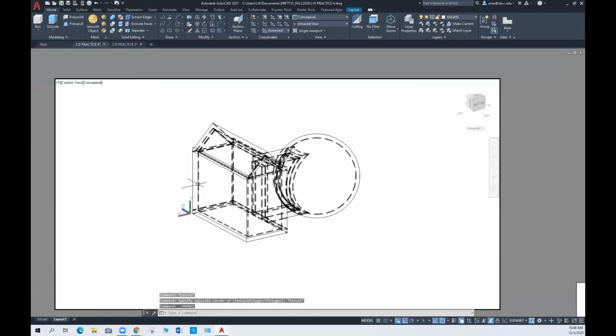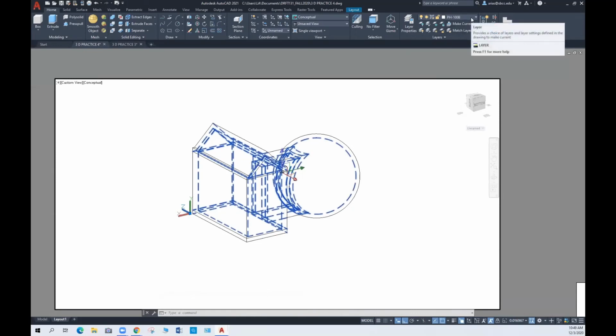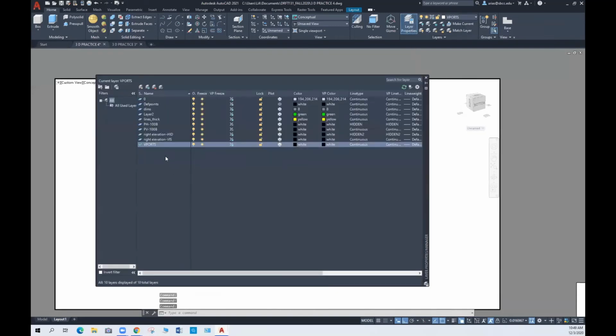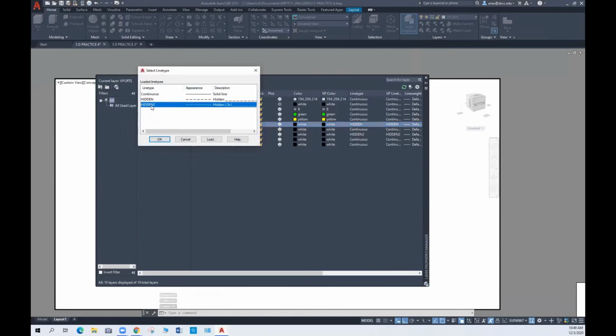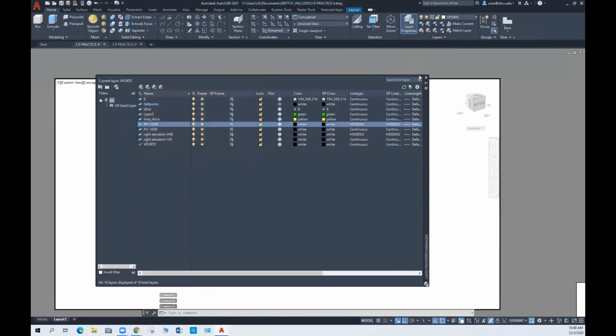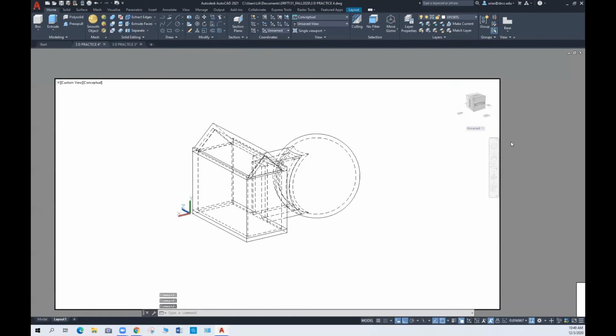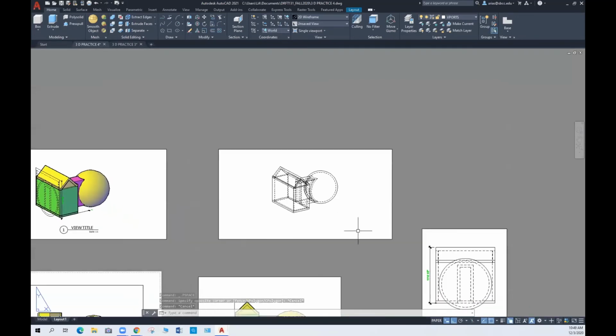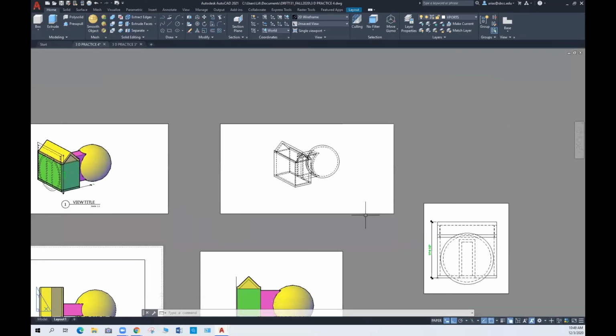And so if I look at that PH 100 hidden lines layer, so go to properties, PH 100, it says hidden. Let's change that to hidden 2. And it gives us a better definition of the hidden lines. And that's what Solprof can do then.